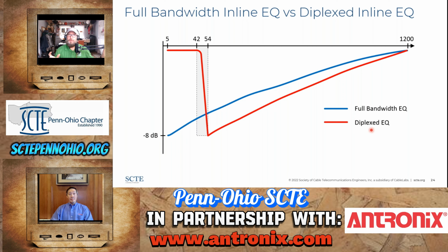But at your lower value taps, your transmit levels are also lower because your upstream path loss is lower. Again, attenuation being a function of frequency. So the companies that wanted to keep their transmit levels higher, because level often equals signal quality, would put in a diplexed equalizer, or in some cases even taps that had the ability to increase the attenuation in the return path to keep those transmit levels high.